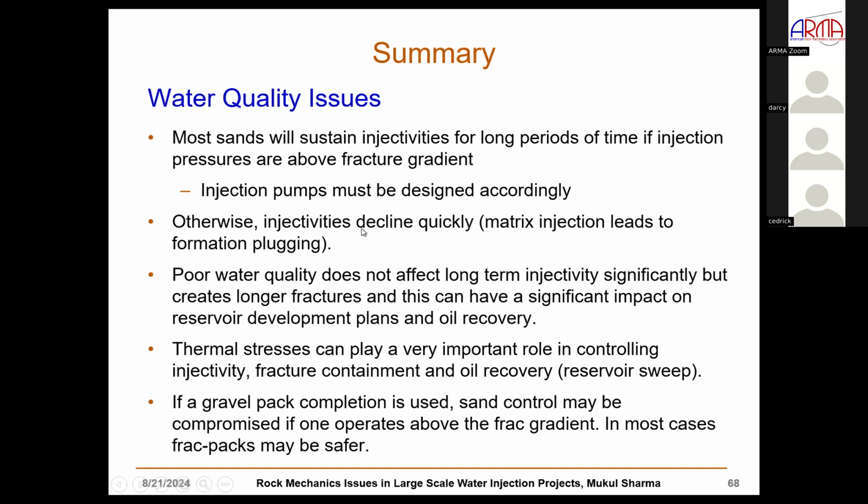Otherwise, if you don't inject above the frac gradient of the sand, then matrix injection will lead to formation plugging and very quick declines in injectivity. This is almost universally true. There are very, very few exceptions to this. Poor water quality does not affect long-term injectivity.